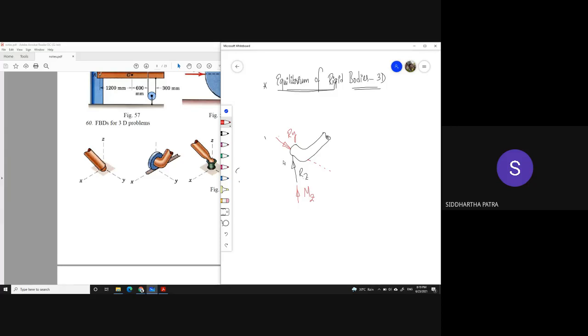And the x-axis, it is free to slide, but can it rotate about the x-axis? If the channel is such that the wheel cannot leave the channel, the wheel cannot be misaligned with the channel. Those are not shown, but those are implied with the tiny shape that has been provided to the channel. So if it cannot leave the channel, do you think it can rotate about the x-axis? If it cannot, then there would be a reaction moment preventing it.